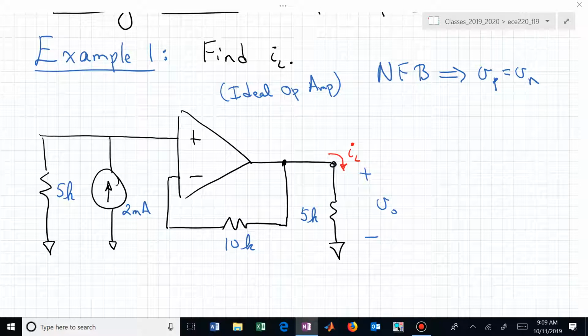We said we were exercising, right? Need to loosen up. What do we need? Or what can we say now? Can we say anything more? It looks too different from what I'm used to. Well, let's just start thinking through this. Do we have anything happening here? What's I sub n? Pardon? 0. The resistance is really big going into the op amp, so this current is 0.